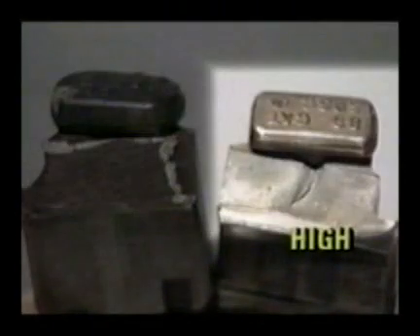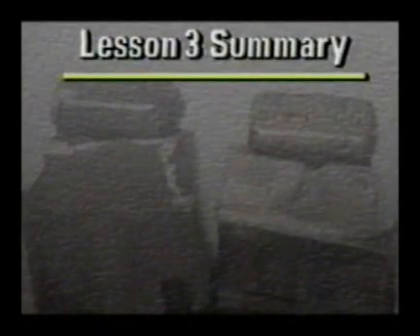The one on the left is low-cycle fatigue because it has several rough textured fatigue cracks starting on the top and right-hand sides and also has a large ductile final fracture. The one on the right is high-cycle fatigue because it is smooth with closely spaced beach marks and a small final fracture.